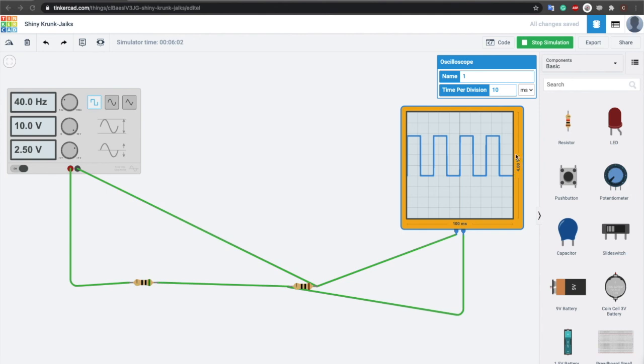Now we can start to read the voltage measurement. So as we said, each division here is equal to 4 divided by the 10 squares, which is 0.4. So each square is 0.4, and our signal is almost 4. We can say it's maybe 3.9. So the voltage will be 3.9 multiplied by 0.4.